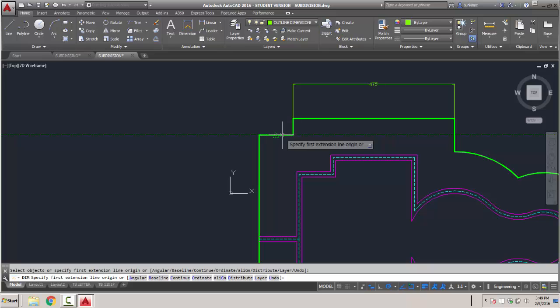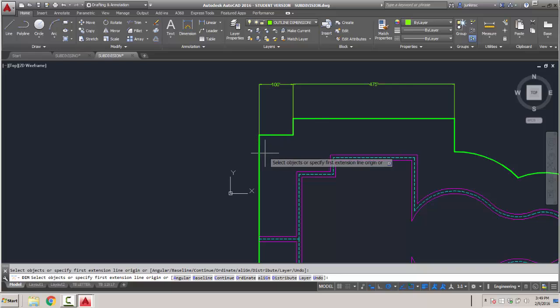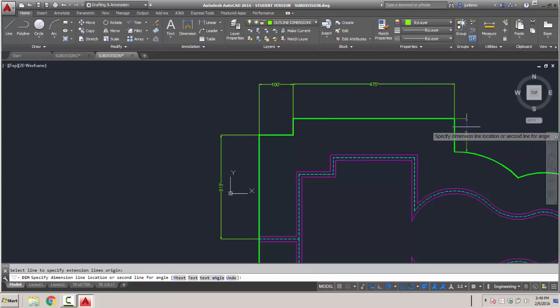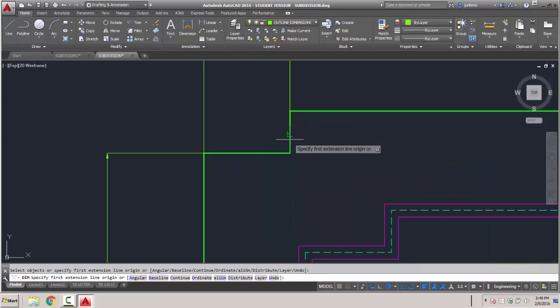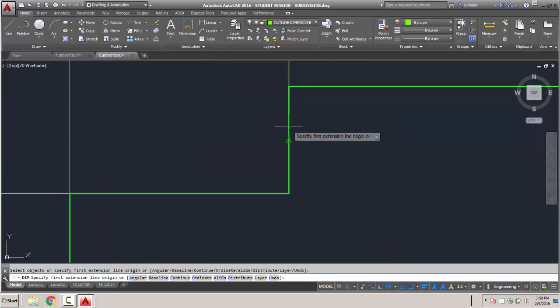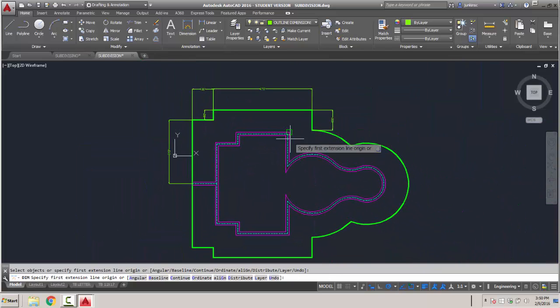And I'll just pop these in. Wants to get that dimension line. Just hit escape. I'll grab this endpoint and just bring it up here where it belongs. Now we'll try it again. Dimension. There it is. Just had to wiggle the mouse a little bit. Okay, there's our dimension lines for the outer portion.